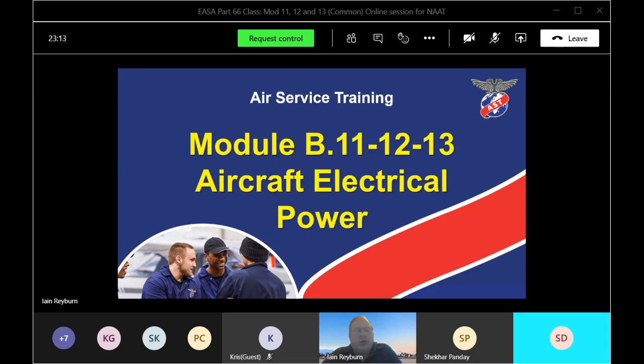These are basic relays. You're all electricians, you understand these relays, or you're all mechanics. This is basically how a relay works. I'll just give a quick highlight on this one. If I put this switch down, I'll get current going through this coil. That'll produce a magnetic field, and that's now going to cause those contacts to change over. As you can see down here, I switch one thing off, put another thing on. So that's how a basic relay works, or all relays work, to be honest. Complex, I can turn things on and off.